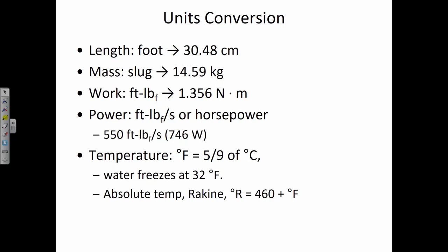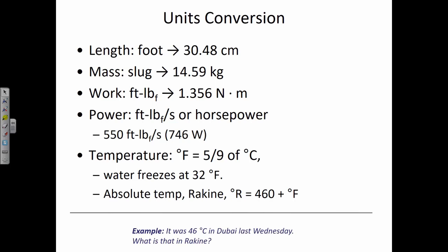But temperature is important in baking, and so I found myself over the summer doing calculations of, if you're adding flour and water together and they're both at different temperatures and you want the mixture to be a certain target temperature, how much heat do you have to add to the water? And so I was using absolute temperature because you get your calculations to work out when you use absolute units of temperature. It wouldn't work out if you were using the relative scale of Fahrenheit like it would for Rankine. So, all right, just to give me a break from talking and give you a break from listening, let's try an example.